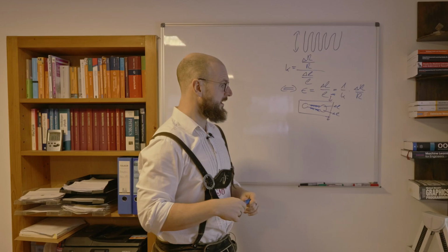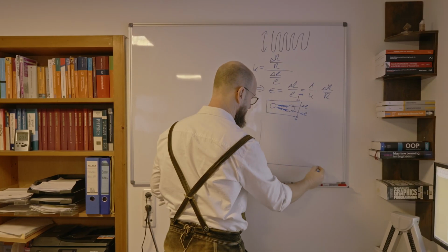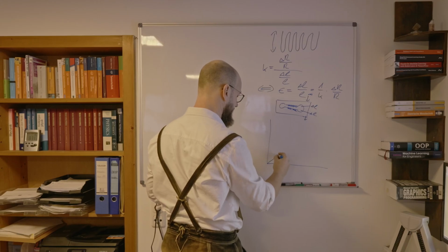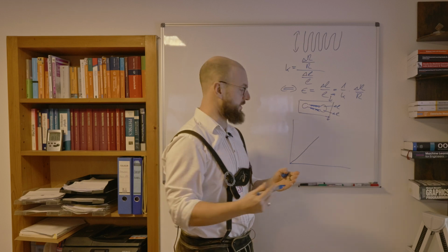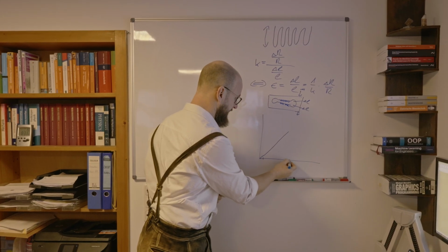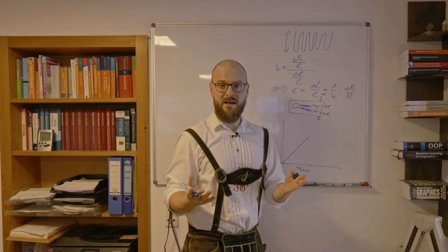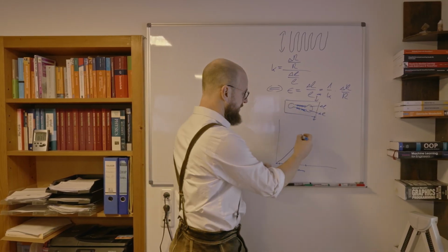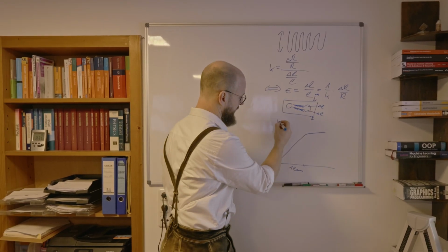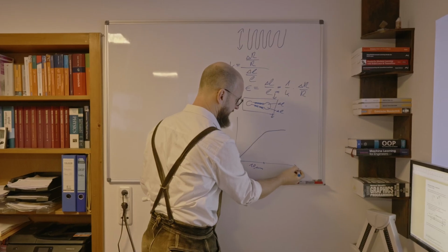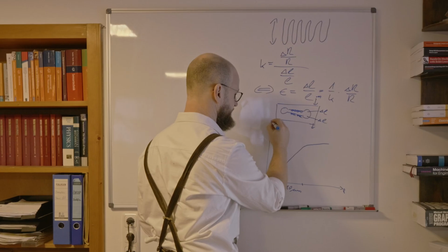So, talking about those length scales, one thing has to be mentioned. Those strain gauges have a very linear behavior for very short distances. So meaning we are, for example, stretching that thing for 10 micrometers. And then suddenly at some stretching range, we get the problem of non-elastic deformation. So when that's the stretched length and that's the resistance,